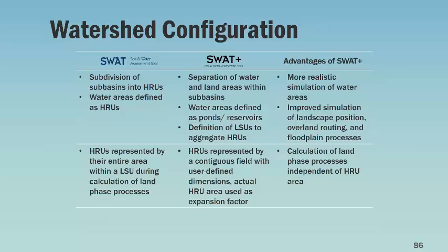I'm not going to read through all of them. In general, it's going to give you more flexibility in terms of how things are connected. So for example, if a HRU in the watershed divide area is directly linked to another HRU or another one downstream, you can connect them directly. You don't have to go through the channel process to get from one place to another. So that could be an overland connection, a subbasin connection, or an aquifer connection. All those can be customized heavily in the new system that we are developing.